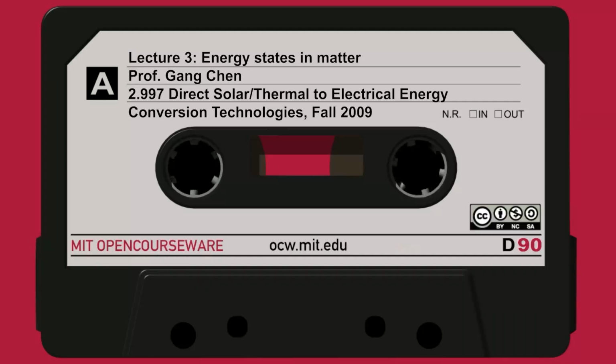But in most cases, at this maximum or minimum, the first derivative is 0, so I have the second order term. Mathematically, it's a Taylor expansion. So here, for example, I take E minus E_C, and of course I didn't put a k, this is not 0, so I should put (k_x minus k_0) squared. Here I put the center at the center. This is a semi-general form, not the most general form of doing the mathematics, right?